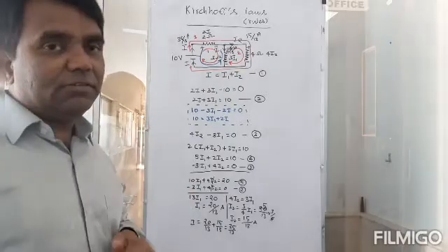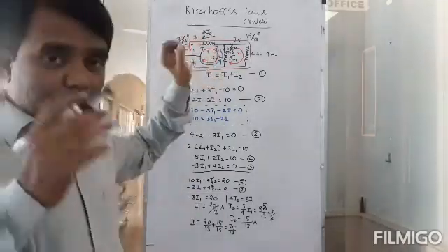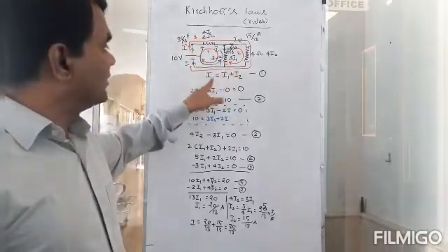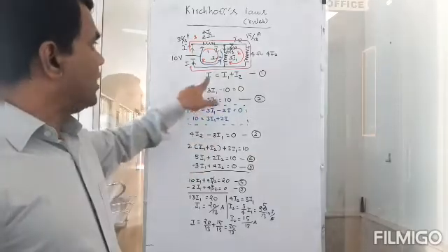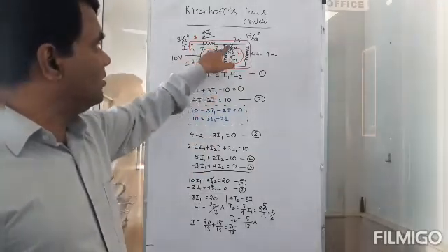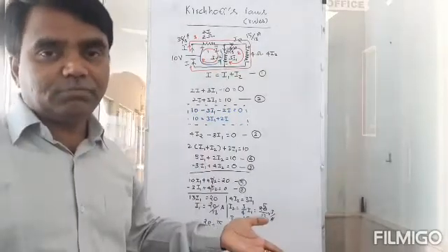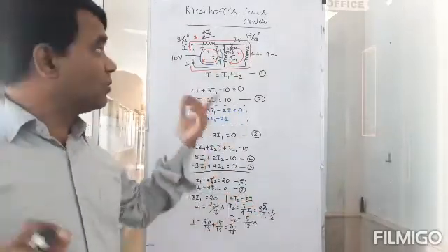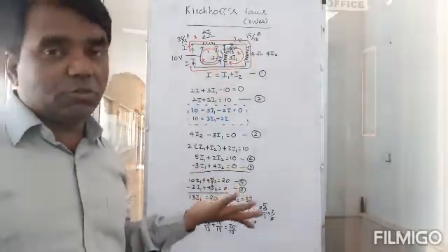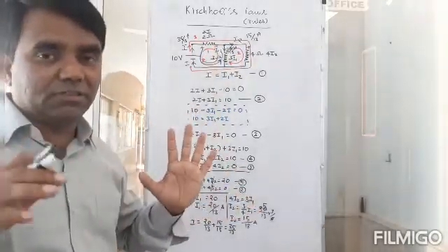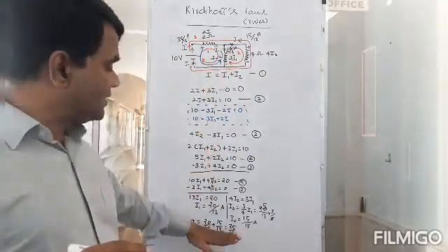I reiterate again. First we had the circuit, and then I chose a junction, and at the junction I said the incoming current is equal to the outgoing current. So I is equal to I1 plus I2. I chose directions. It's totally up to you. I did not know that I2 will be flowing that way or I1 will be flowing this way. But I chose a random direction. Okay. So then I got these numbers.